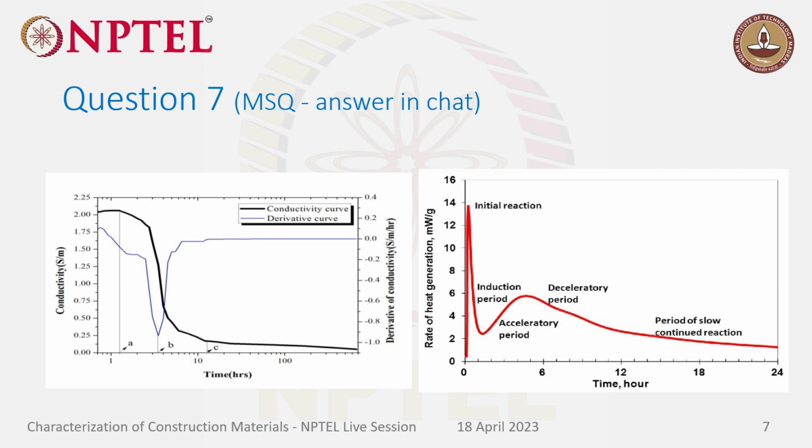If you add cement to water, the water will wet the cement and the ions like calcium, silica, alumina, and the rest of the alkali ions will come out of the cement into the water and they start to react, right? So the dissolution of ions decreases during this time, after the immediate heat of wetting.